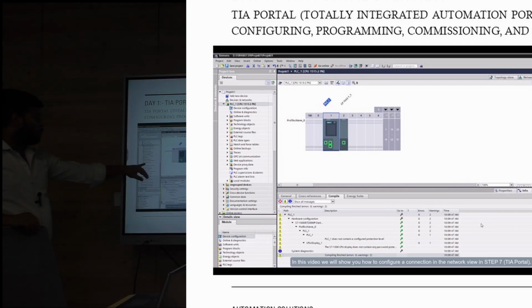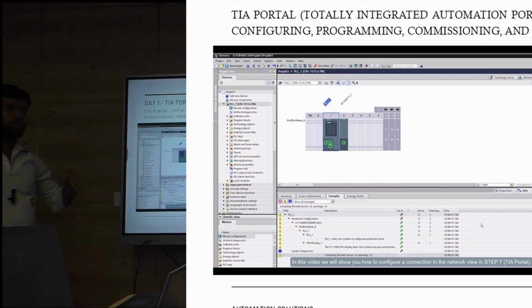Here we have OPC UA communication. If we want OPC UA communication, we need to configure it here. It acts like Modbus, which is also used for data communication and data transfer. But Modbus can be connected to devices, whereas OPC UA is connected to servers.